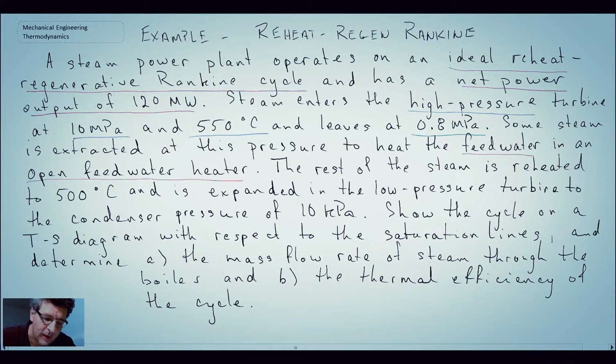We've discussed two different types of feed water heaters, closed and open. This is one of those types, and that tells us a little bit about its design. We then go through a reheat process back up to 500 degrees C at the 0.8 MPa. Then we go through a low pressure turbine all the way down to the condenser pressure of 10 kPa.